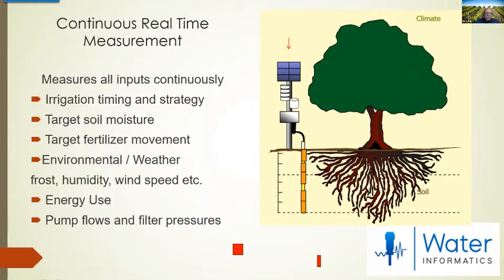Our ability to look at pump flows and filter pressure is super important. Right now, as spring startup occurs, we're seeing filters plug. As those filters plug, specifically in a sand media, we're starting to see silt loads go into these sand medias. The sand media will flush based on a differential pressure, and when that keeps happening, let's just say the filter flushes every hour.